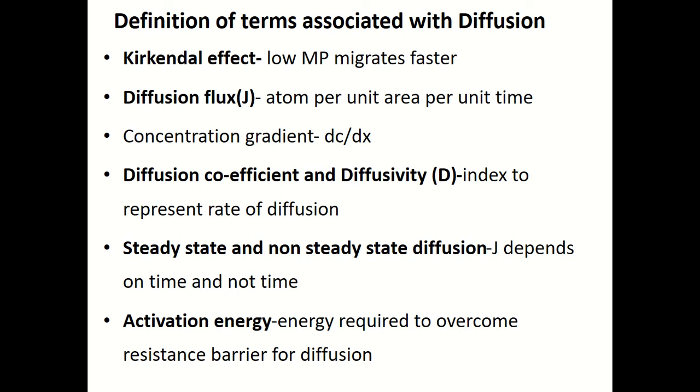Whereas in the case of non-steady state diffusion, at any given instant, flux at different cross-sectional planes along the diffusion direction are different, or not equal. The diffusion flux changes with time. So the flux at a given cross section is a function of time, that is non-steady state.